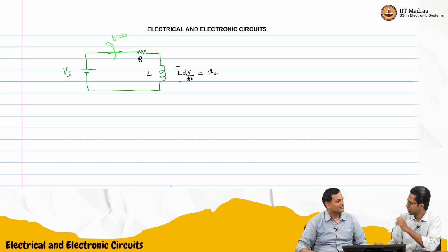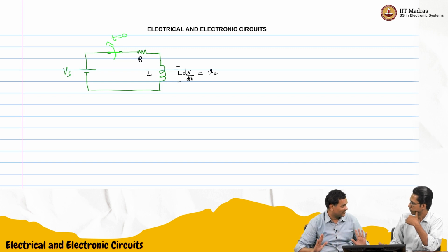I got some idea, but let's say I want to generalize this a little bit. I have an inductor, and I am moving a switch, either closing or opening, in this case opening. Let's say 0 minus, how will I represent it? Maybe we look at it systematically. As soon as you open or close the switch, we need to figure out how to handle the inductor, correct?